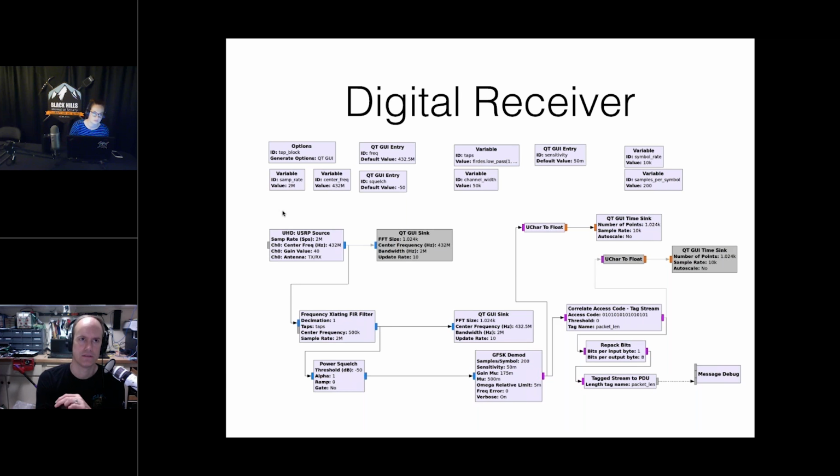So to get a little bit more into RF engineering, just as a general rule of thumb, the speed at which you can transmit data is going to be proportional to the bandwidth that you're consuming. And so even something as affordable as the HackRF is going to support 20 megahertz bandwidth. So you can actually shove data out of this thing pretty quickly if you want to.